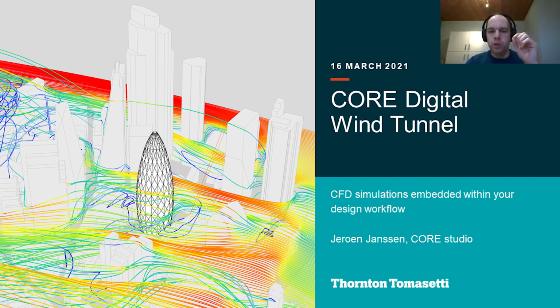For the super tall buildings and the very flexible ones, often you do go to the more complex high frequency force simulations, the aeroelastic simulations, where in the wind tunnel you model the building so that it actually moves and flexes with the wind.